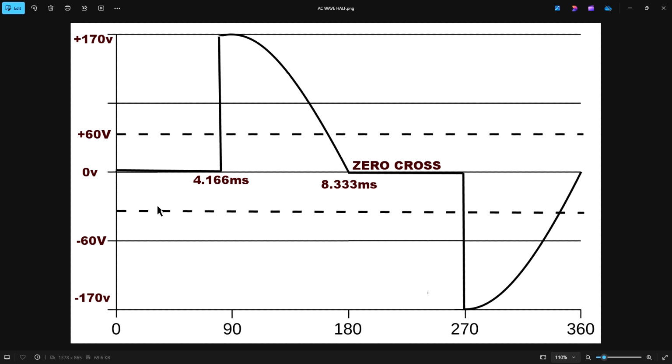Now, what would this do for us? Notice that we have a lot less area under this waveform, and so our average voltage would be, I'm just using 60 here to give you an idea since 120 was full, let's say 60 volts. We would have 60 volts average. So what would we use something like this for? Well, how about a dimmer? How about the dimmers that you slide up and down on the wall to control the lights in your house? Often they're nothing but a Triac with a device that actually does this for you.